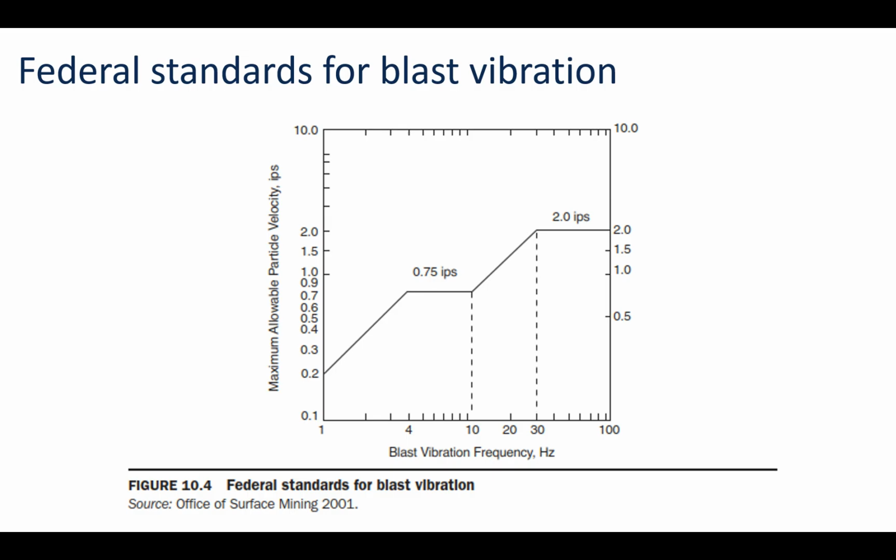Here are the federal standards for blast vibrations. You have the blast frequency, and then of course the maximum allowable particle velocity. So as your blasting vibration frequency increases, the maximum allowable particle velocity also allows for an increase.